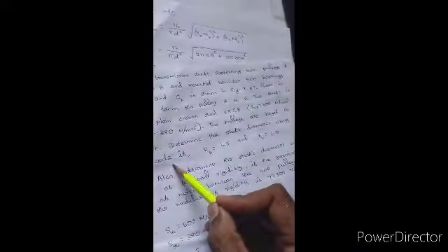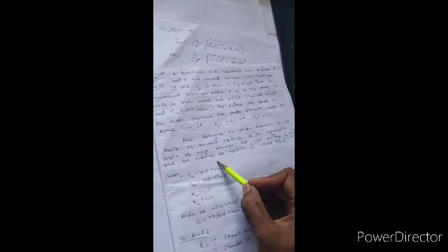So they told us to find the shaft diameter using the ASME code. The second time, we have to find the shaft diameter using the torsional rigidity method. Two methods we are going to use in this problem. The permissible angle of twist between the two pulleys is 0.5 degree, and the modulus of rigidity G is 79,300 Newton per mm square.